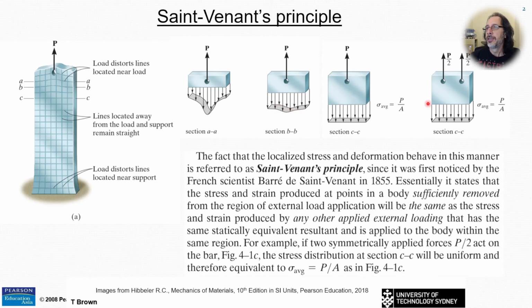The other way of thinking about Saint-Venant's principle is it doesn't matter whether we apply the load via one hole like this and have P, or whether we have two holes and the load is applied in half through the two loads here. So whether we have P or P over 2, doesn't matter. Around the loading area, of course, it will be different, but at some distance away from where the load's applied, the stresses and strains are independent of the loading and also of the support.